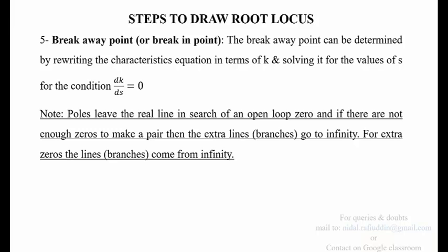That particular point is called the breakaway point, and from that point the two roots or the poles moved in the opposite direction. Had these been zeros, then they would have been arriving from infinity, crashing at the same point and coming to the imaginary axis. So breakaway point is the term used for poles, while break-in point is used for the zeros of the system.